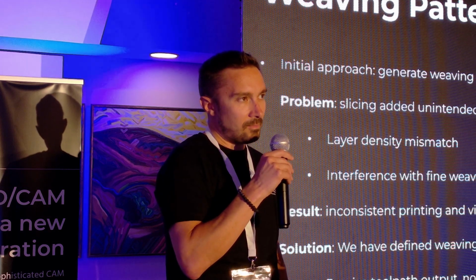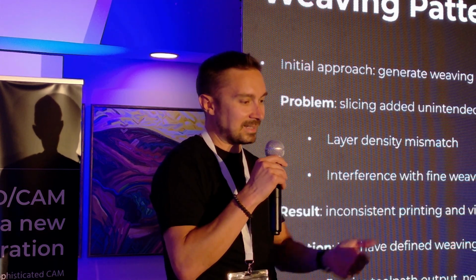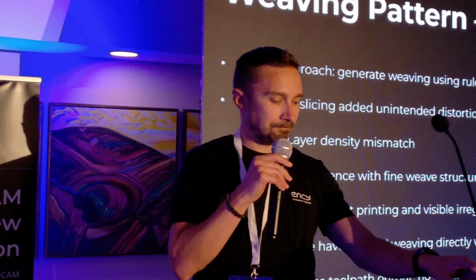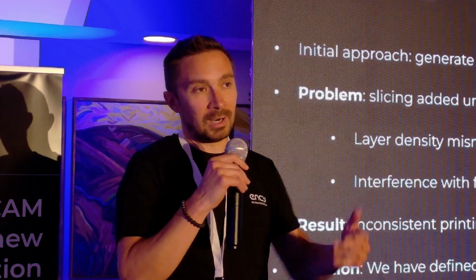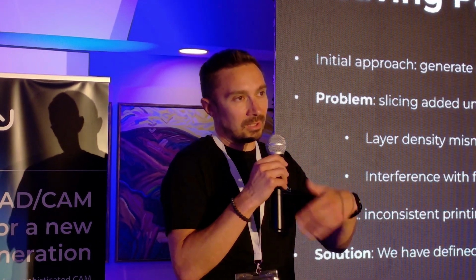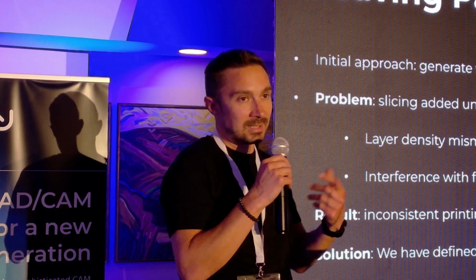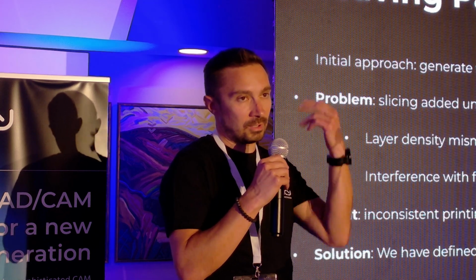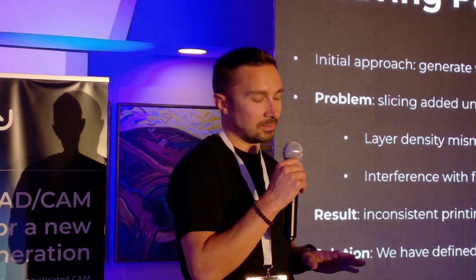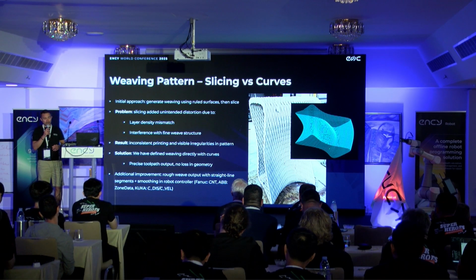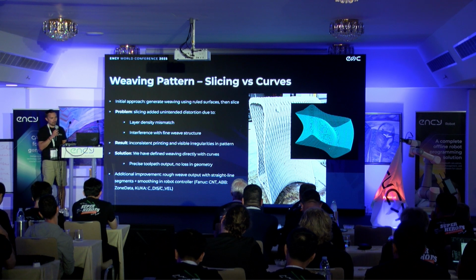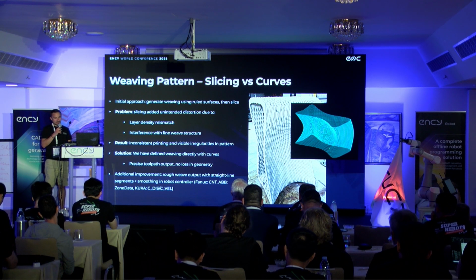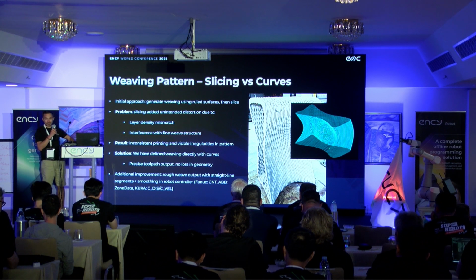And I made the decision to do the same, but with normal 6D contouring operation, which is not a part of the additive package, but we can use this operation for additive manufacturing, and ask the designer to generate for me just lines without any surfaces. And we have a successful case here, and we were able to do a perfect pattern.